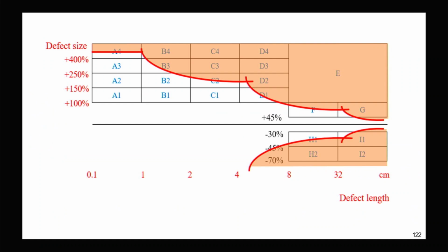So during winding, we can set the cutter setting based on a certain curve. Where we want to remove the faults, the shaded area, we can set our cutter, and as soon as the type of fault reaches within the cutter zone sensor, the cutter will cut that portion and then splicing will act.